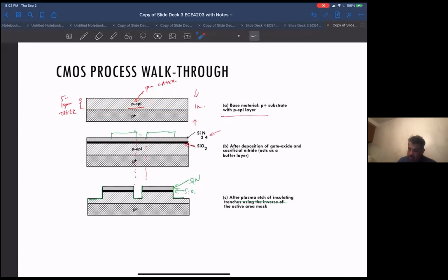So the first thing you do is you pattern this wafer, basically etching into the silicon. These are the isolation layers between transistors. So this is really the only time you've etched through silicon. You've removed silicon to put isolation between your transistors, which will be sitting here and here, and you want them isolated from each other. And this is one of the few steps where, because your etchants are so strong, with your lithography steps,